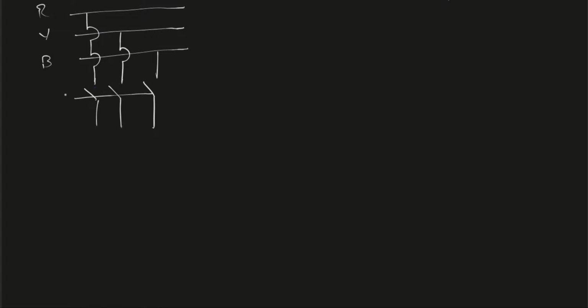The symbol of a 3-pole MCB is like this. I have explained before, right? From the 3-pole MCB, it's directly connected to a power contactor. From the power contactor, it goes to an overload relay. This is an overload relay.